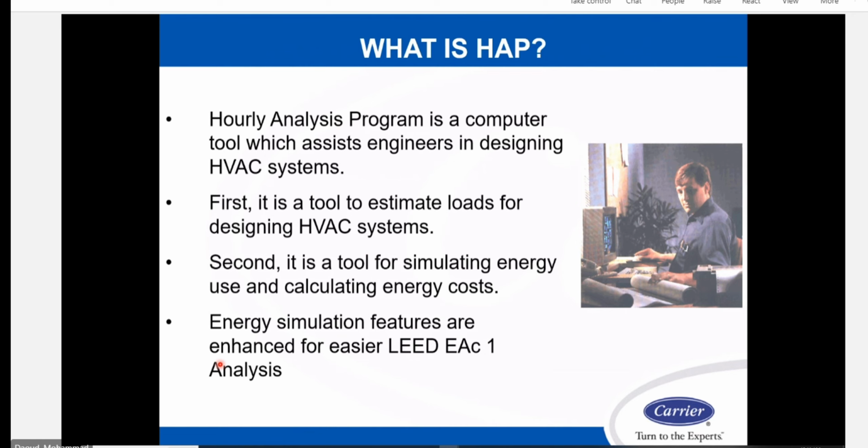HAP is a computer tool which assists the engineer in designing the HVAC, and it can estimate loads for designing HVAC, simulate the energy, and calculate energy costs. By the way, it can calculate energy costs for both HVAC systems and non-HVAC systems for the entire building, like elevators, lighting, pumps, etc. And it is also compatible with LEED. We can just take the reports of HAP, if you have a LEED project,